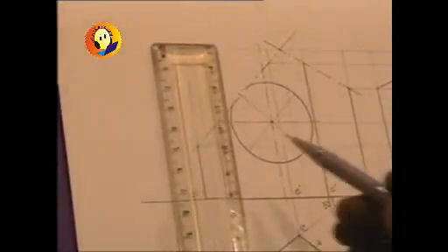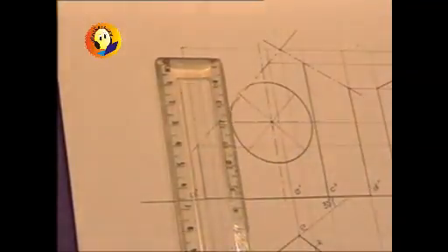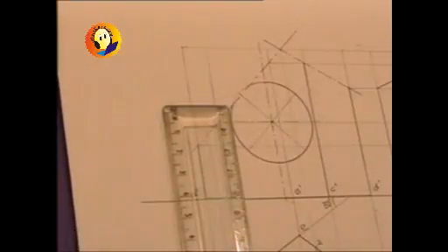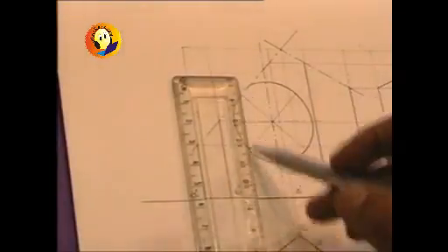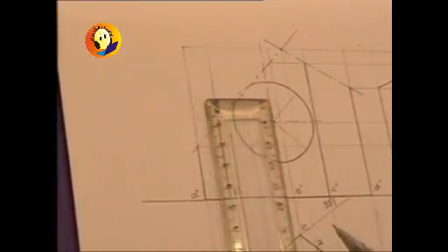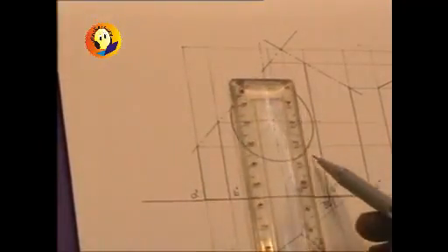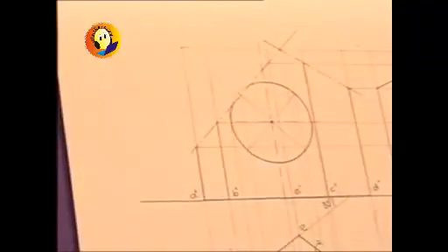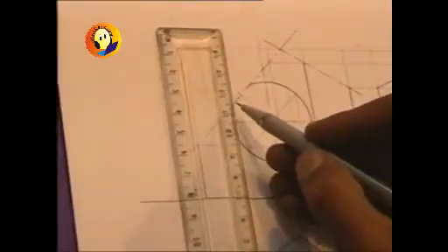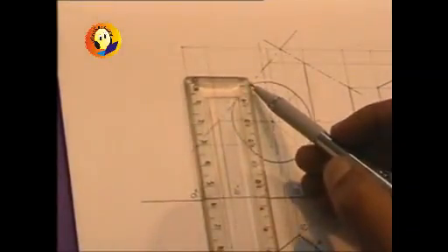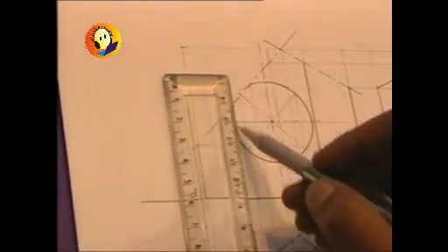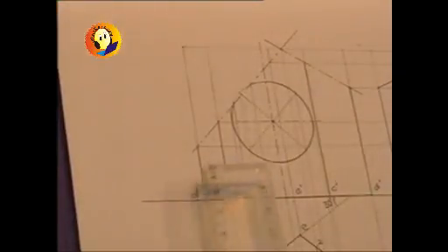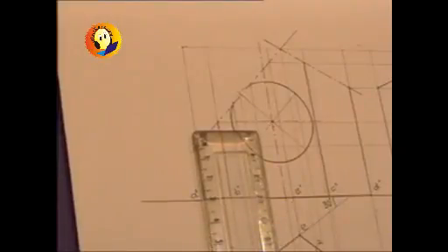And then through these 8 parts draw projectors, and so you will be getting a number of projectors over here. And all these projectors should be drawn and should be pulled up to the top view. Also the 2 points at which the circle is cutting the cutting plane, those 2 generators also should be drawn. And even they should be taken all the way to the top view.